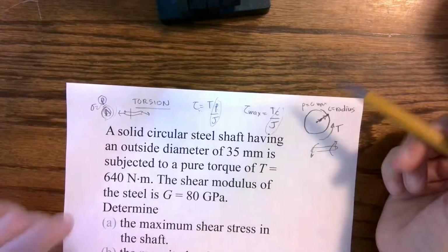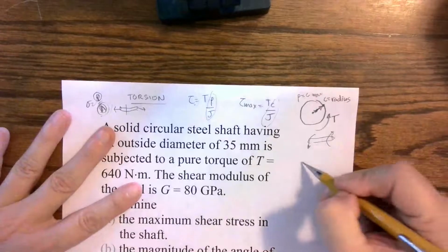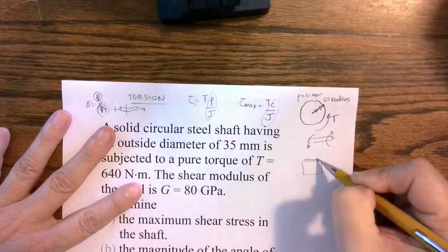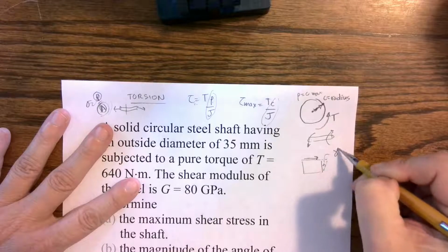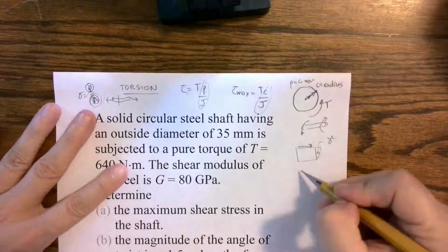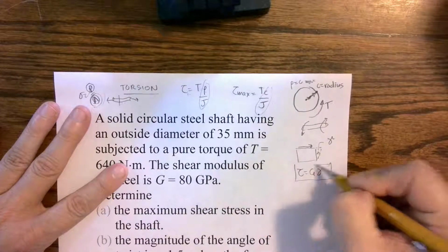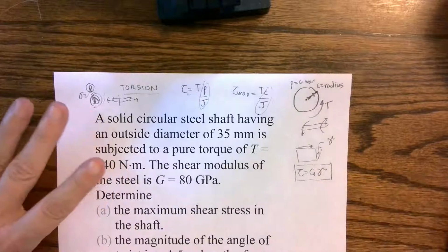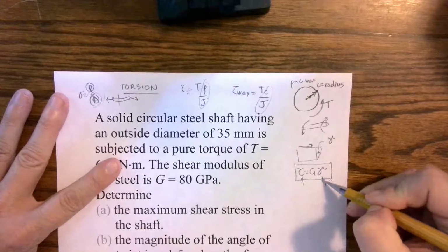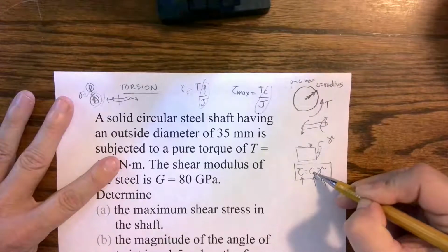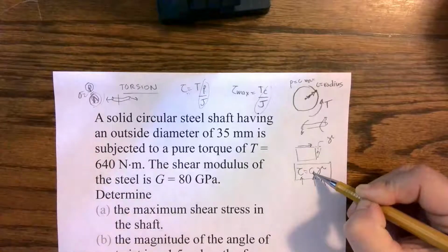With shear stress, we have to recognize, what is shear stress? It's parallel to that cross-sectional area, and it's going to cause a distortion where we have shear strain. So it's like our stress equals E times strain, except now we're looking at the shear version. We have shear stress, we have that deformation that occurs, and that deformation is a function of our material property. This is the shear modulus of rigidity, or the shear modulus.